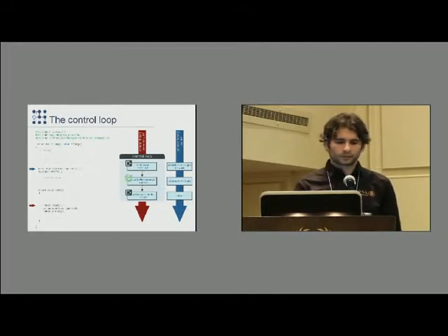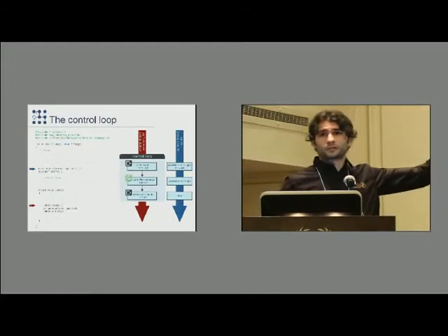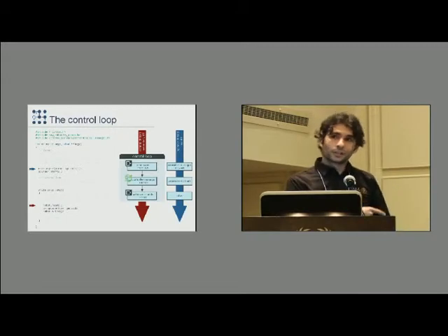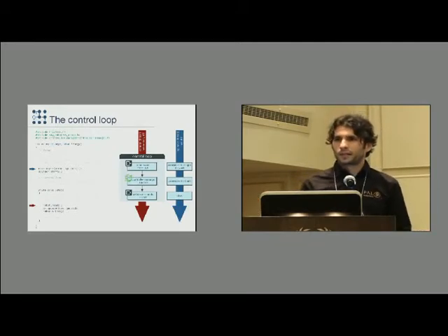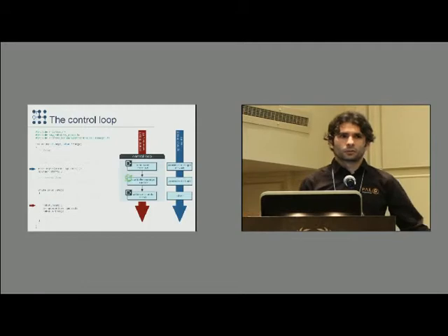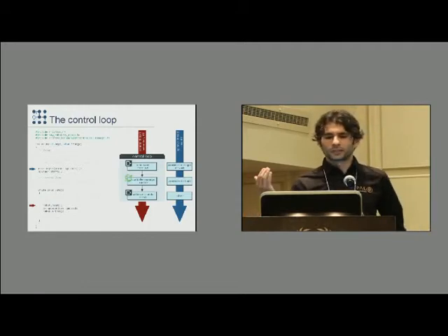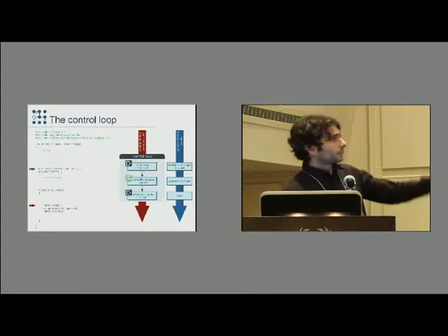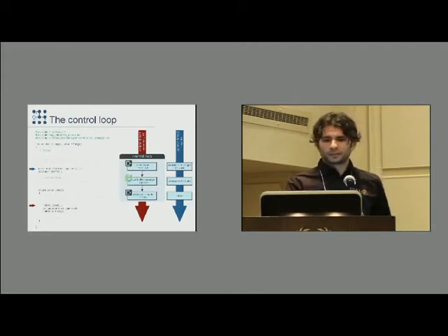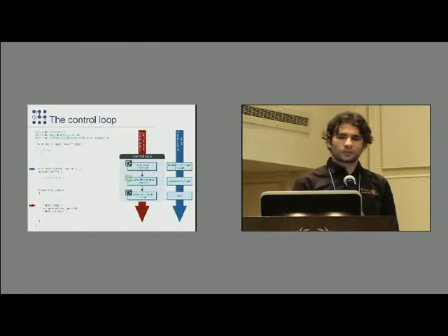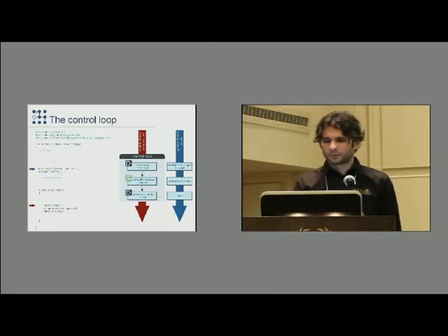And by non-real-time, I'm talking not only about respecting requirements from real-time applications, but also deterministic execution. In this case, we don't have real-time constraints. It's a slow robot, it's 10 Hertz. But here it also makes sense to have these separate. Say you have a controller that, when you load it, needs to parse a URDF, and you have a URDF with, say, 10,000 joints. There is no way to guarantee that parsing that URDF will take less than 0.1 seconds. So if you serialize everything and put everything in the same thread, these operations will make you not respect your deadlines in the control loop. This is why all of those things, even if you're not using a real-time operating system, you should have them separate in a spinner thread.